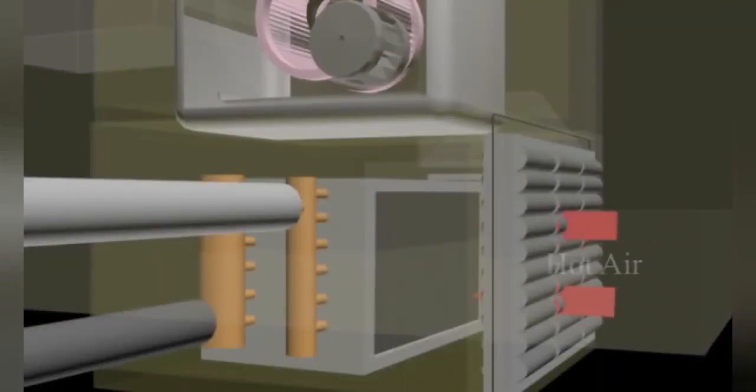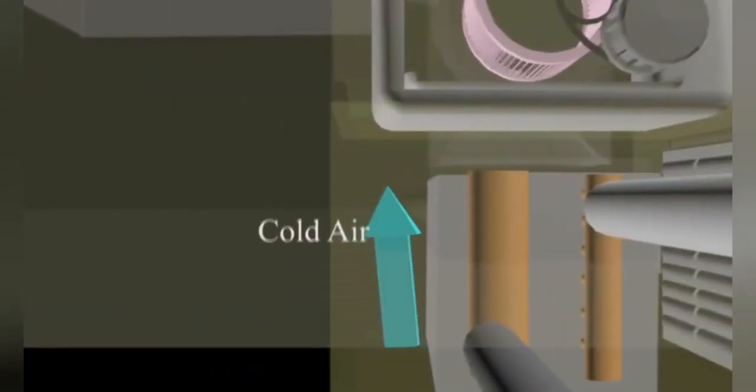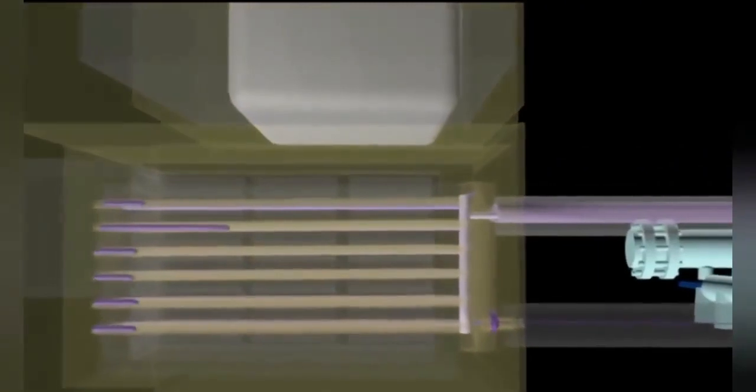In the cooling coil, the hot air will go through the cooling coil and switch to cold air due to the heat transferred to chilled water. Cooling coils commonly used in this system are tube and fin. After absorbing heat from the hot air, the chilled water will be known as chilled water return. Normally the chilled water return pipe will be colored light blue. Chilled water return will return back to the chiller to transfer the heat absorbed to the refrigerant in the evaporator.